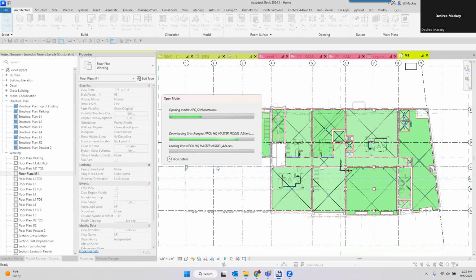Now, since I can't publish coordinates, I save the site locator model. I then open up my building. I bring in the site locator model and I align it to those 2 grid lines, and I go into elevation and I align it. I'm not moving the building, I'm moving the site locator model. Now that it's in there, I can acquire those coordinates.